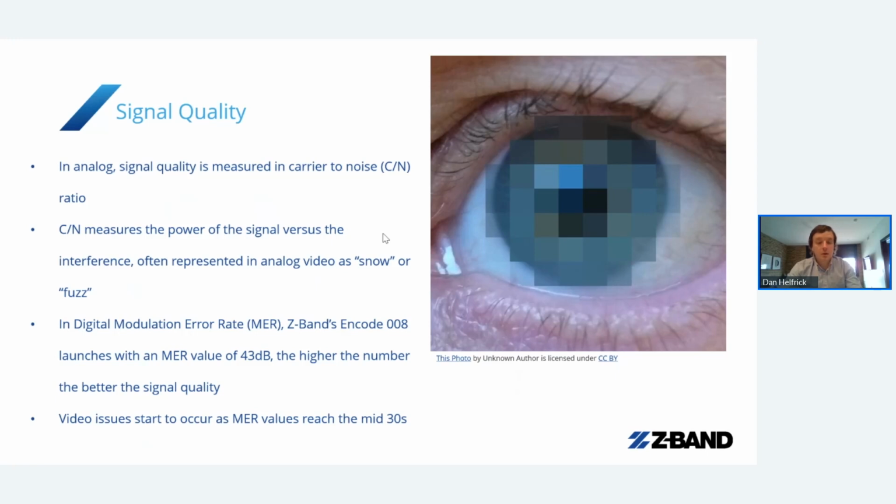But really, those are the three things that we look at, right? Are we troubleshooting the right channels? What's the power level on those channels? What's the quality on those channels? Those are the three things that we're going to ask about every time, right? And one of the issues that we have as Z-band, and really as cable TV companies, all of the folks that we work with, is having clients with the equipment to be able to give us this feedback.